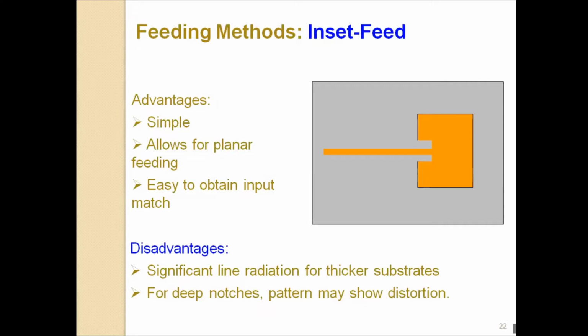We know that every antenna has its characteristic impedance, right? The characteristic impedance is very, very important for communication. The whole world lies in the characteristic impedance. If the cable impedance is not proper, the signal cannot be delivered. And if the antenna impedance is not equal to the cable impedance, whatever power supply you give and however good the antenna design, the signal will not be fed into the antenna, right?